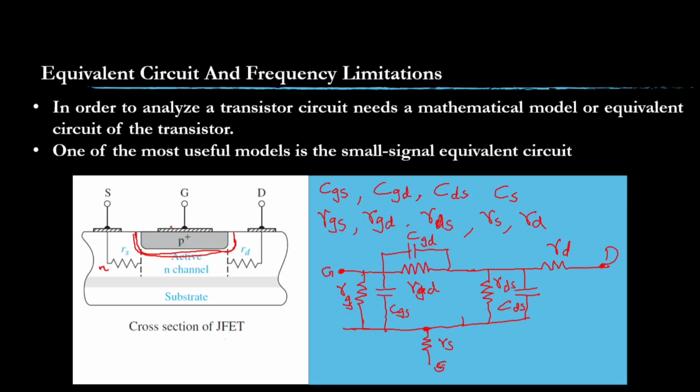And we know when I apply voltage from the source to the gate, current flows in this N-channel JFET, with electrons flowing from source to drain. Then the current will be from drain to source, so again I cannot neglect it while drawing the mathematical model. I need to represent that current also. The current depends on the input voltage VGS, so it is a dependent current source. Current will flow in this direction, drain to source, and depends on VGS.